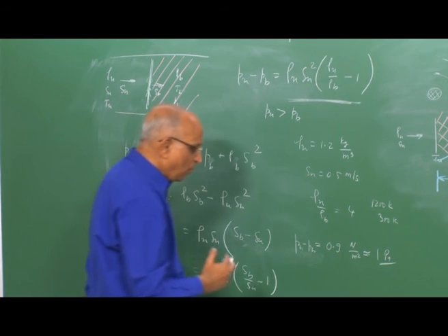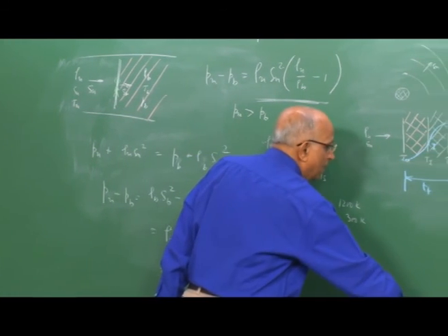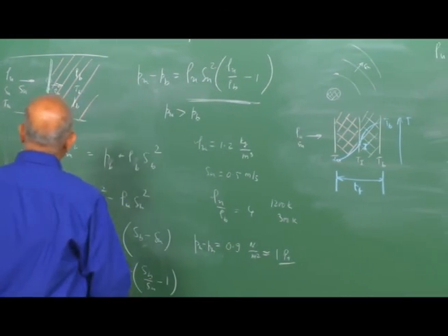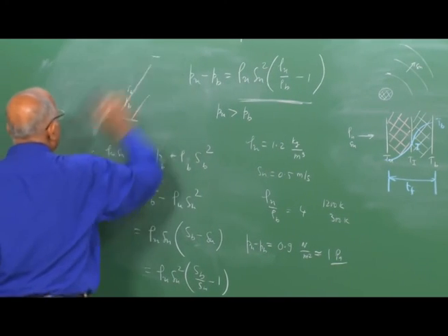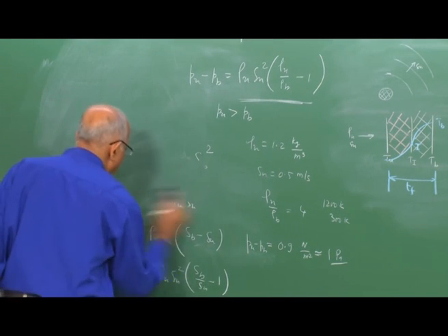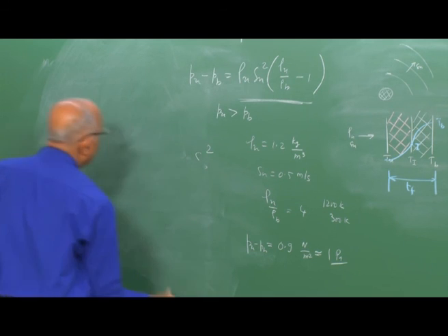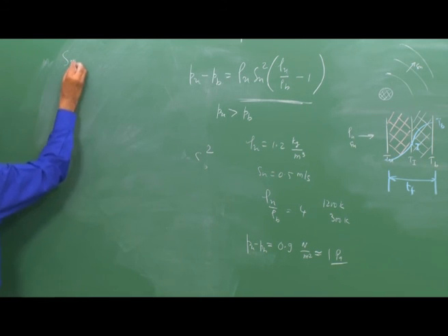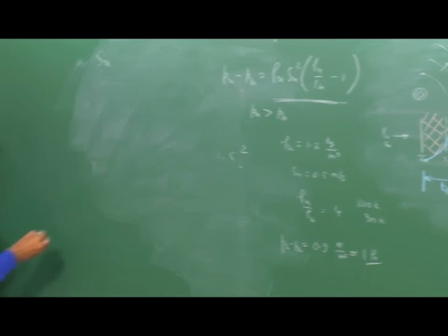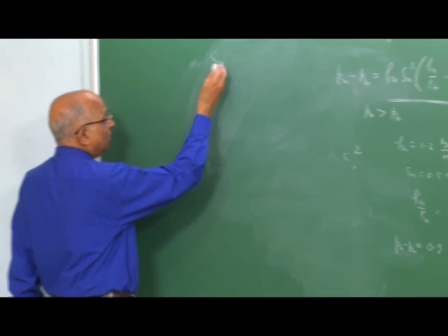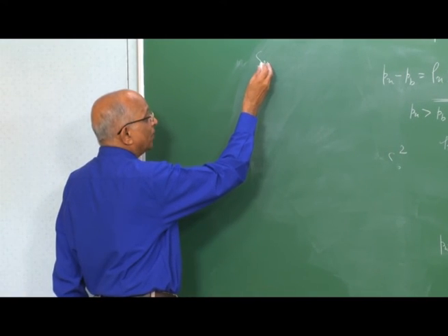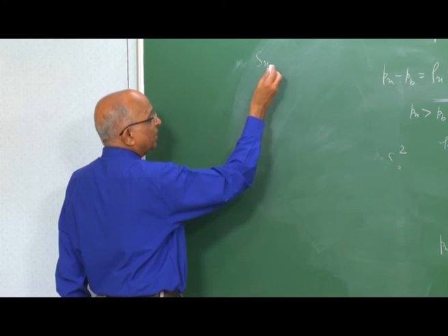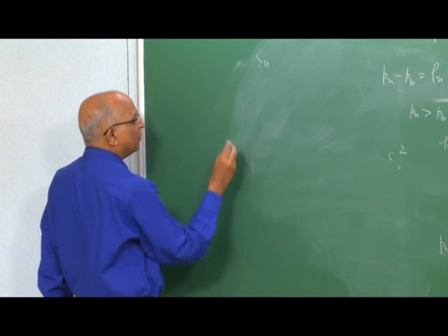Therefore, so far what is it we did? We have learned the following. We learned how to determine the value of the flame speed SU, which is the velocity with which the combustion front is moving into the unburned gas medium, which we said for a stationary medium is the same as the flame speed.